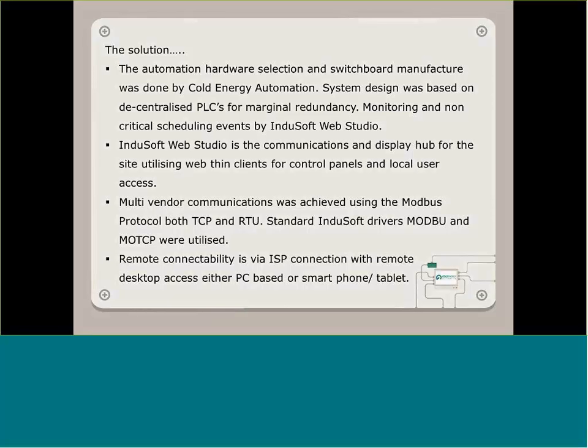The multiple vendor communications was achieved using both Modbus RTU and TCP protocols again. We used the standard libraries from InduSoft. They worked great. The remote PC and smartphone access was again just through remote desktop. Worked fantastic. Really gave us an avenue to do modifications and also further development on the site.